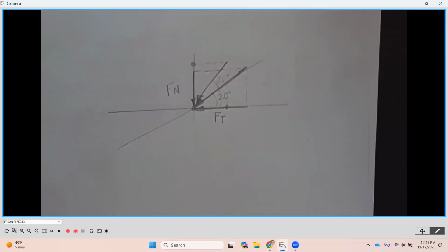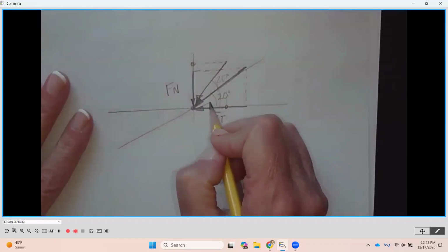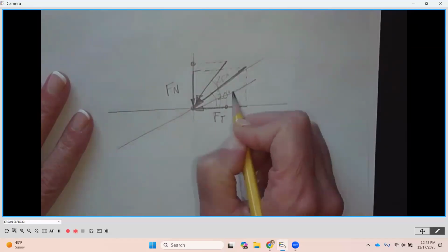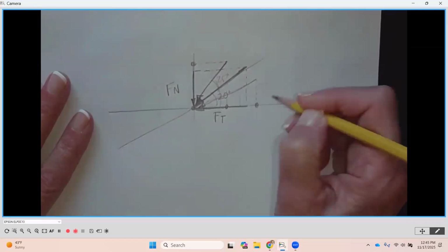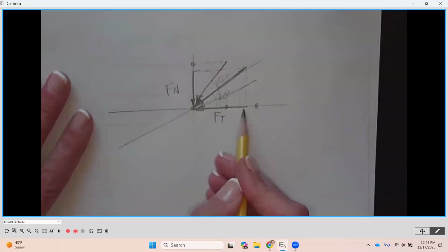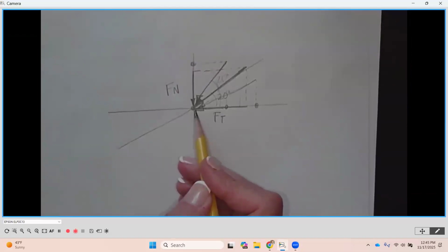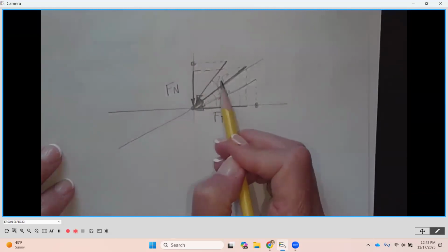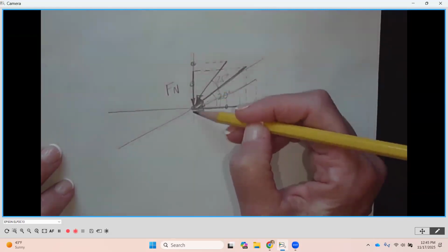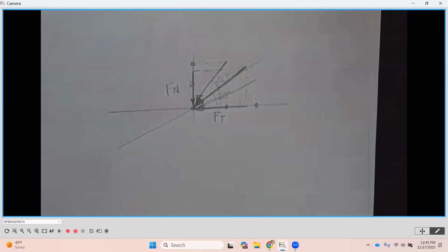Okay, 14 and a half. If I move this down to 14 and a half, something like this, same force, look what happens here. This time, at 14 and a half, my tangential force is going to get longer. So now I have an increased force along that horizontal axis, which is going to increase the amount of pitting, or the sooner I'm going to get pitting. It also increases the risk of shearing off that gear tooth. And I'm making smaller the force pushed down naturally where there's more material.